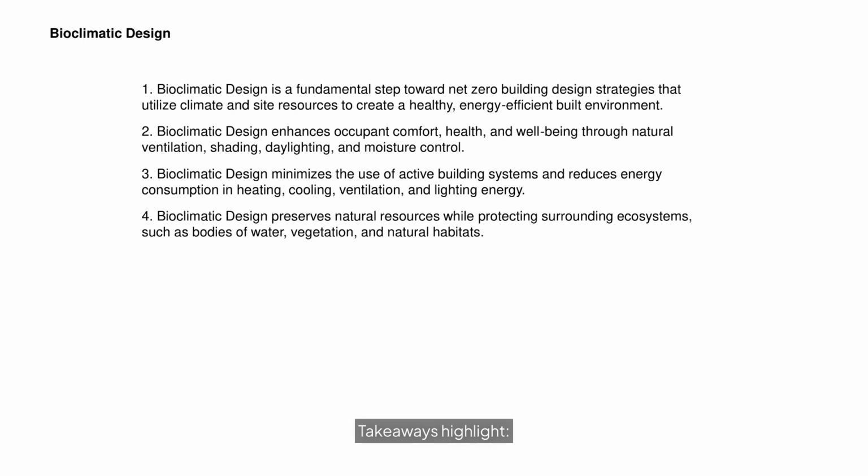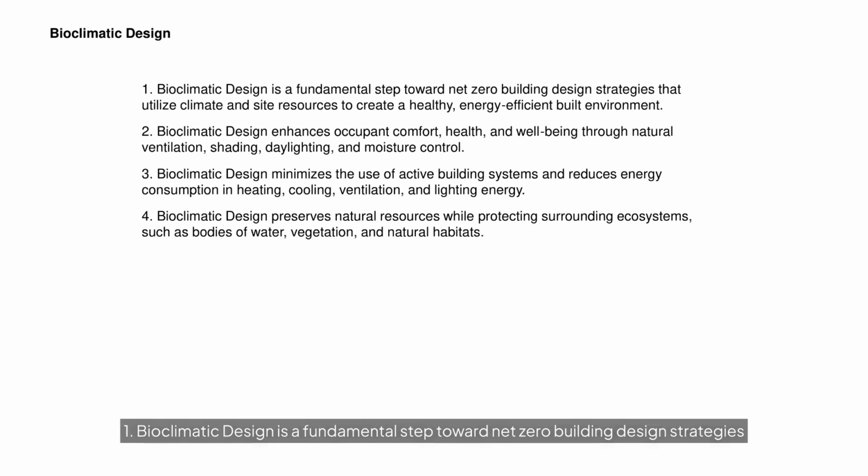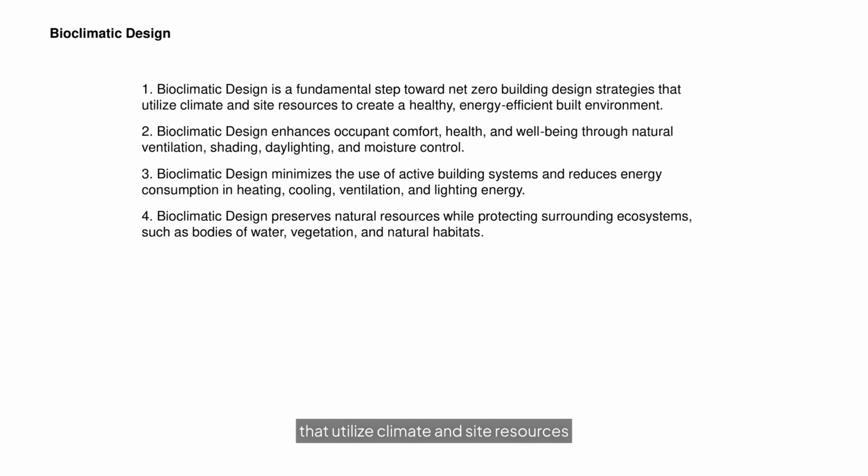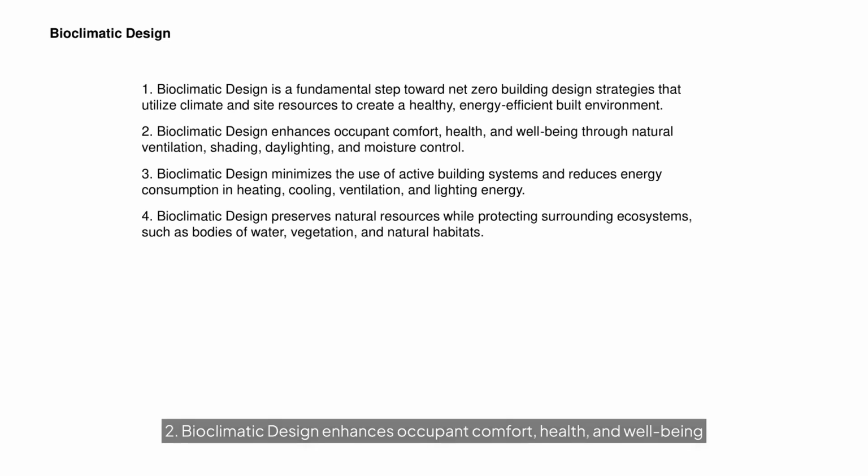Takeaways. Highlight 1. Bioclimatic design is a fundamental step toward net zero building design strategies that utilize climate and site resources to create a healthy, energy-efficient built environment. 2. Bioclimatic design enhances occupant comfort, health, and well-being through natural ventilation, shading, daylighting, and moisture control. 3.